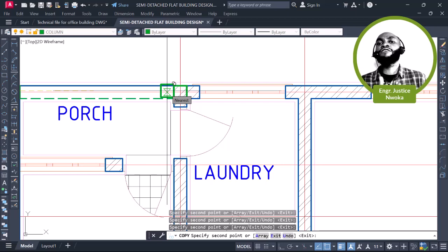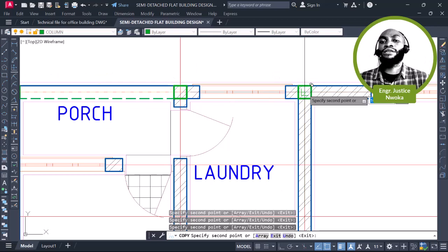But even for a small residential building for just a normal client, that means you are just wasting the client's money, because you will have a bigger diameter of reinforcement, like Y20 and all that, and a bigger section of concrete for beams and that. So don't do that. Just keep yourself below that.